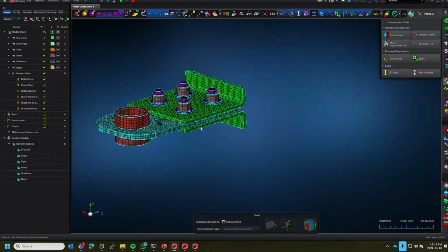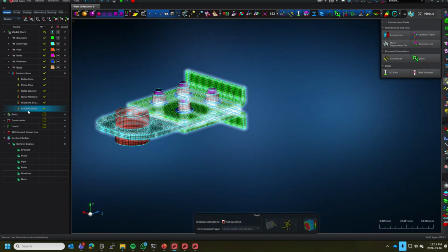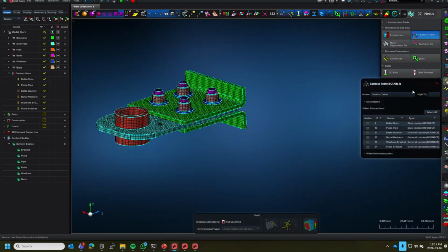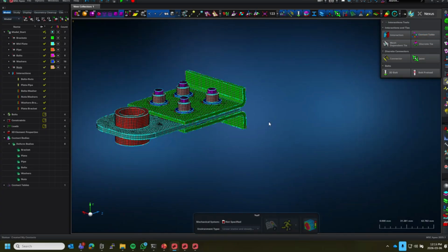Okay, so at this point, we've got loads, boundary conditions, materials, properties, everything except we haven't yet specified which contacts to use together. In this case, I want all of them, obviously. So again, I need to specify a contact table. For the loads and constraints it will be load combination, constraint combination. So my contact, and I select everything. The reason we want to use this is that sometimes contact changes during an analysis, something is touching and later changed to glue or whatever the case would be, then we can use more than one contact table. In this case, we just leave it as is.